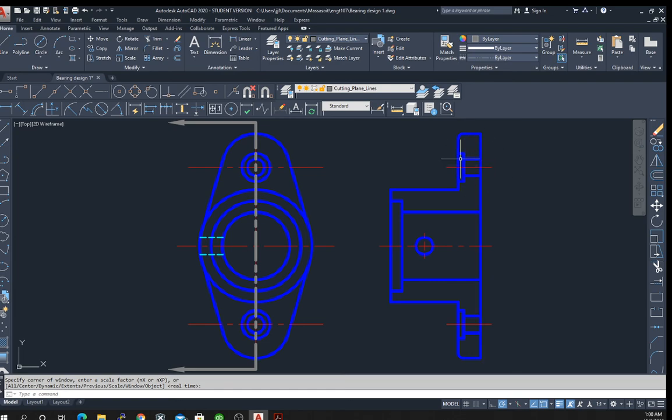These two areas will be holes, so they'll actually be spaces. So these areas will not be hatched. This area here, all of this in the middle, these will all be holes. This will be an indent, and this will be a hole right through the part. So none of that will be hatched. And then on the bottom, the same areas we discussed on the top. This area here and this area here.